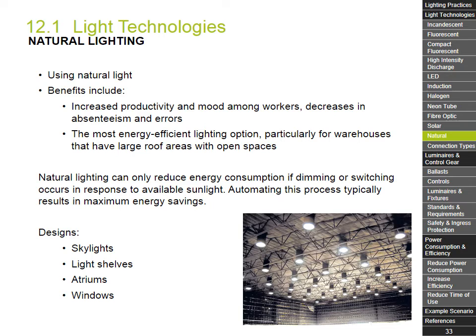A skylight is any window installed in a roof and is simply designed to allow sunlight to light an internal space and is much more effective than a typical window in a wall. Ideal design standards suggest a skylight area of 4 to 8% of floor space, depending on climate conditions, latitude, and skylight characteristics. Light shelves extend out from a window into the inside space.